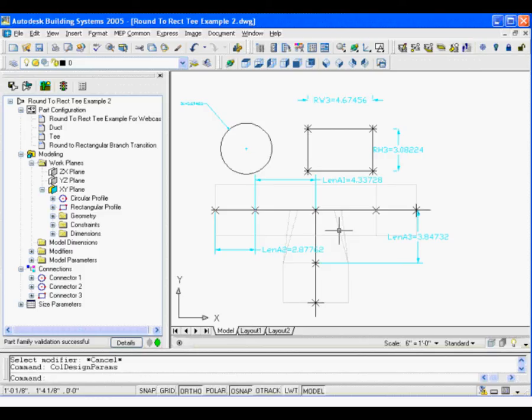Okay. And I know we're running a little bit late here, but I just want to get through the last couple pieces. We now have the sizes that are associated to this part. Now you'll notice that the only dimension I haven't defined yet was this length over here, which was our shoulder length. To edit that, I can come back into my model parameters and simply say Edit.